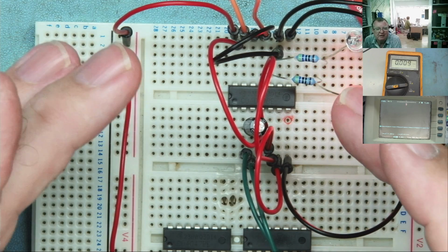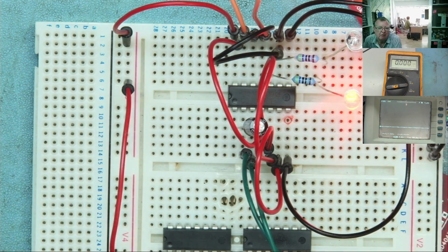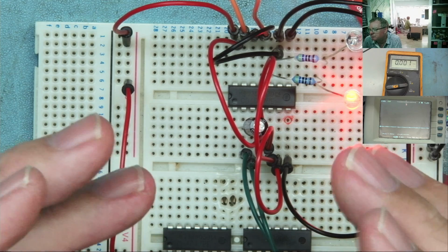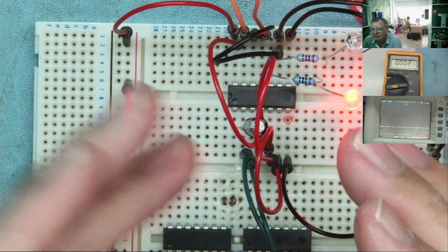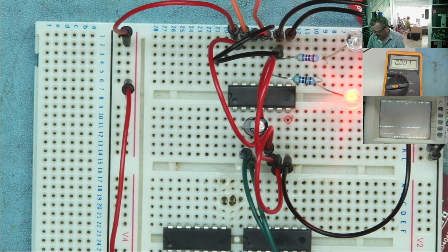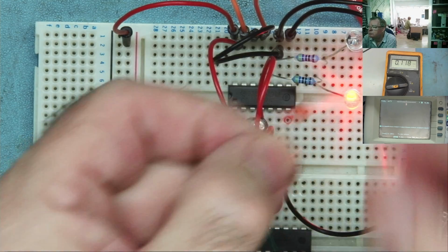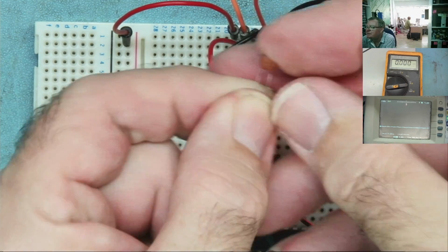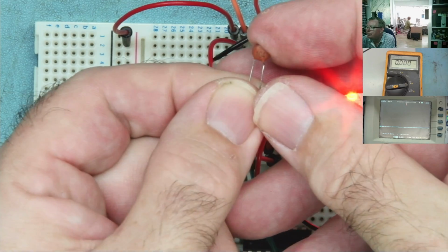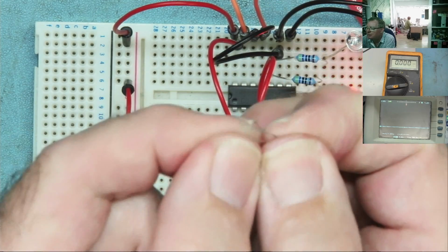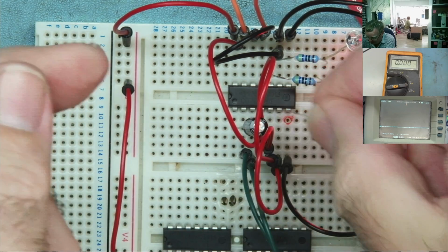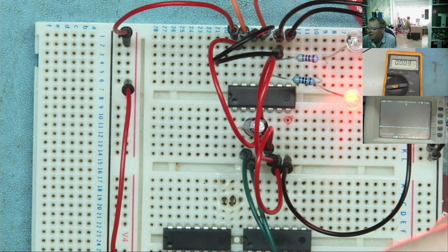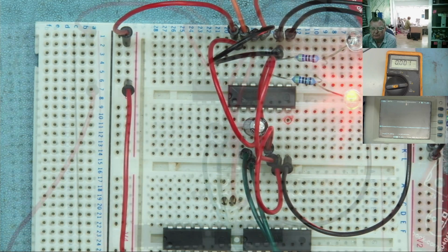So often you find a capacitor directly across the power to ground on these sort of logic chips, very close to the chip. And this is to stop spikes when the circuit's internally is switching, drawing different amounts of power. So decoupling capacitors are often these types, ceramic, 104, 100 nanofarads. I'm going to try and mount this directly across the chip, so as close as I can to the supply and ground pins. And let's see if this makes a difference.